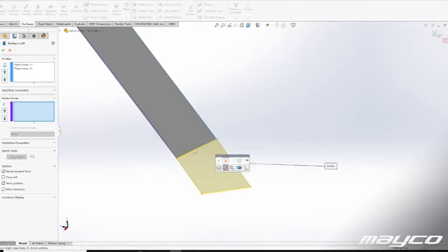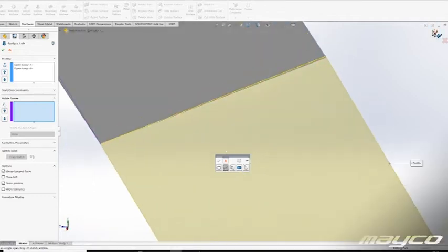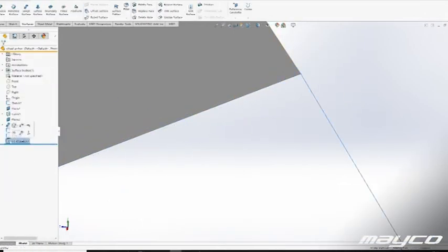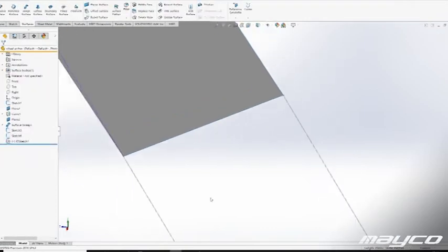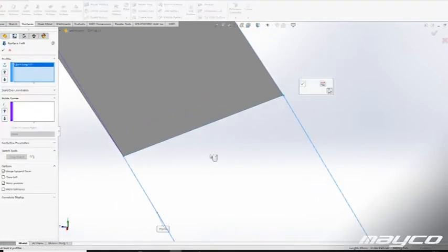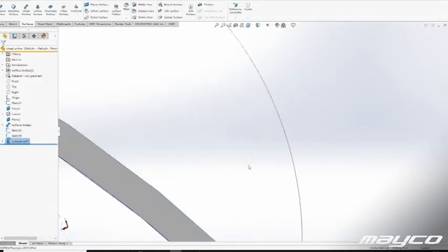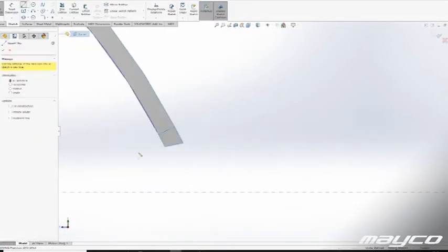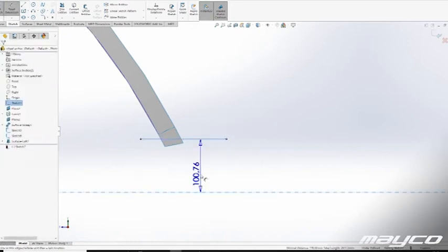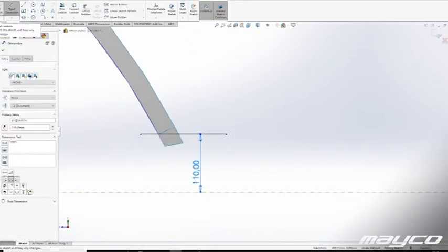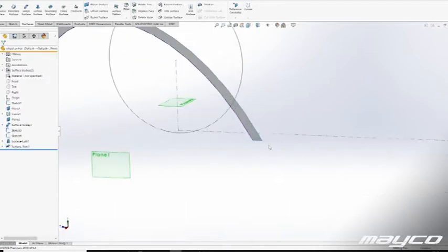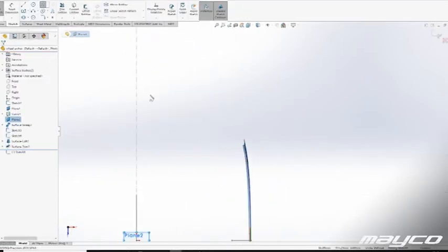What I try to do with this model, to keep it simple, is work with planes. So you saw me do the first surface loft, and then I made a plane on which I could make a new line and work towards that plane. What you do for surface modeling is you have your curves or sketches that are basically for the shape of something.